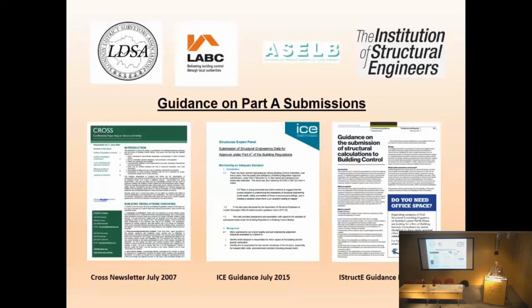The common problems that we find as checking engineers are a lack of a design statement identifying codes, load paths, A3 class and the like, important information. We often get problems where there's no overall engineer that's made himself responsible for the overall design, especially for overall stability, because of the splintered nature of contracts.